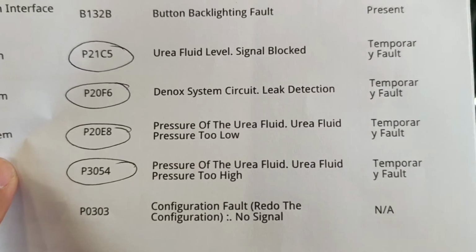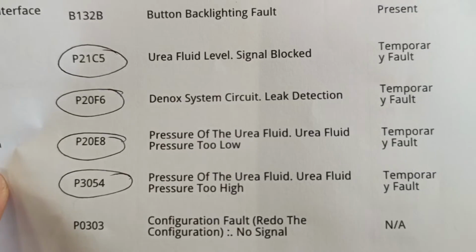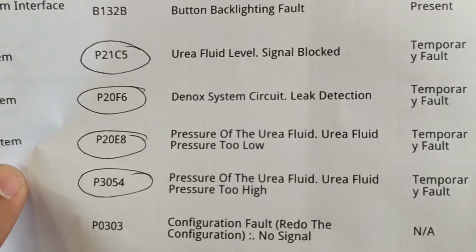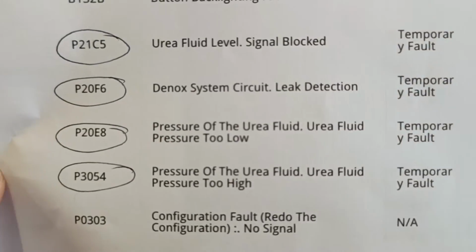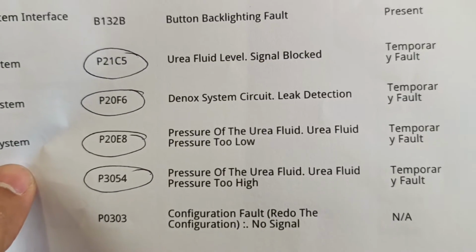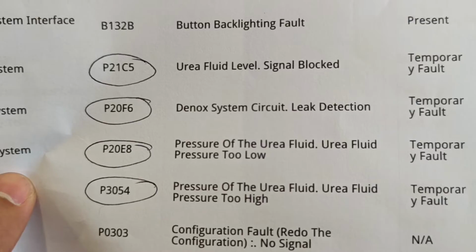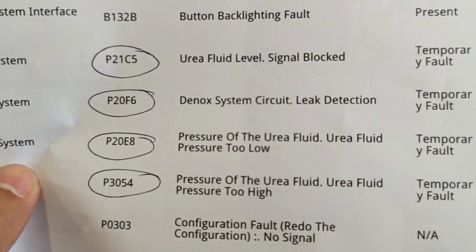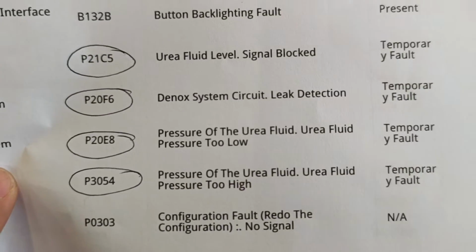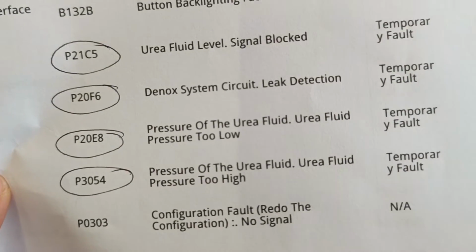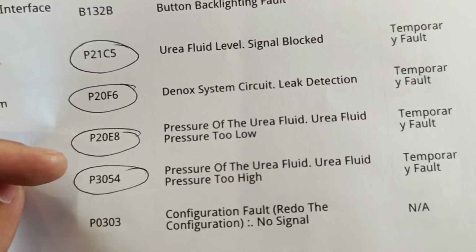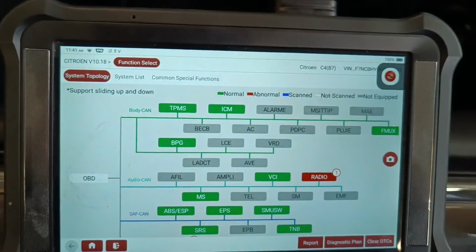So when the car goes to report these faults, it can't report them, and just basically can't bring the light up anymore or the countdown. So DTC deletes are required if you're mapping it out, and the resets. In this video I'm just showing you how to do the reset. If you was fixing it or doing the deletes, you'd need to do the resets, because you're not just deleting these faults. You need to actually go into the diagnostic tool, have a diagnostic tool that's capable.